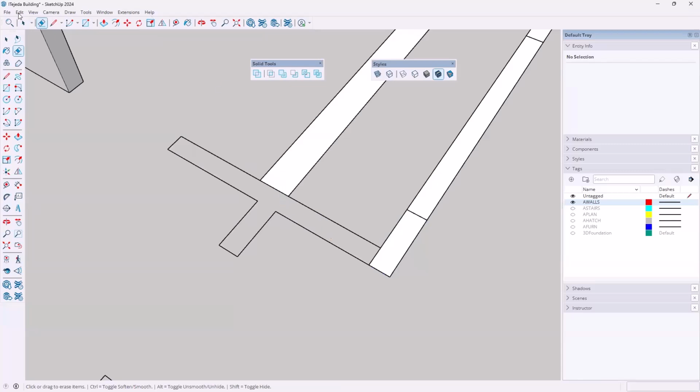So I'm going to undo that and then tap the space bar and then double click on this surface and then delete it. It's sometimes easier just to start all over. So I'm going to draw another rectangle and I'll pick a couple of different corners from what I think I picked earlier. So I'll click right here where it says endpoint, and then I'll take it to this endpoint and then tap the space bar.